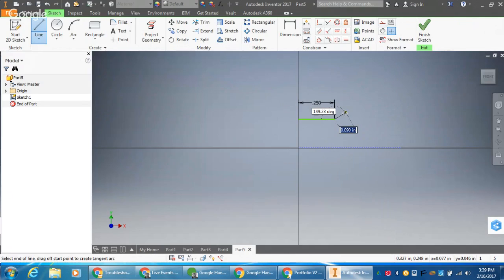So if we're going to be building this shape, I'm going to build it a little bit backwards, actually. Not that it really matters, but let's just start by building this up. So the shape then comes up a little bit, and you have to know how far up it comes, but it only tells us from the center point. So I can just come up here and hit escape, and I can dimension from this point to here.